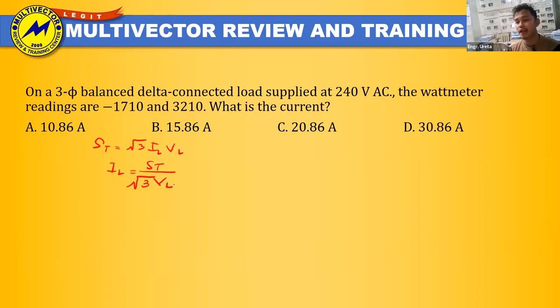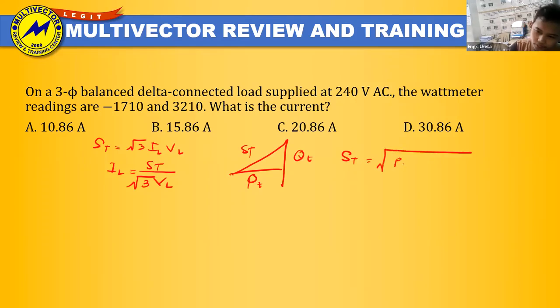In terms of the apparent power, our power triangle has sides ST, PT, and QT. Our ST is just equal to the square root of PT squared plus QT squared. Remember that for the two-wattmeter method, our QT is equal to the square root of 3 times wattmeter reading 1 minus wattmeter reading 2, which is the square root of 3 times negative 1710 minus 3210.